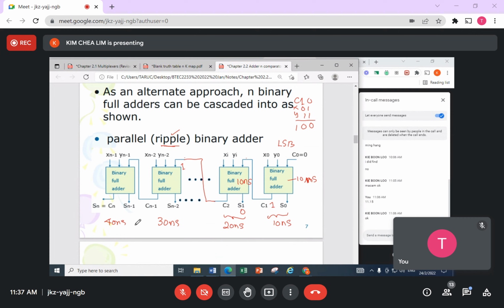All right. So of course, if you want to go for, let's say, 16 bits of additions here, then you must plan your timing. Let's say you are doing VHDL, you must allocate enough time for it to respond. So I only want to see the signal, let's say, after 160 nanoseconds later. So you add in the timing after a certain number of times.